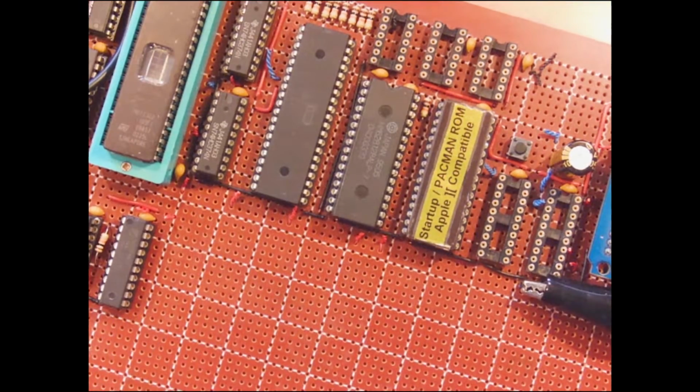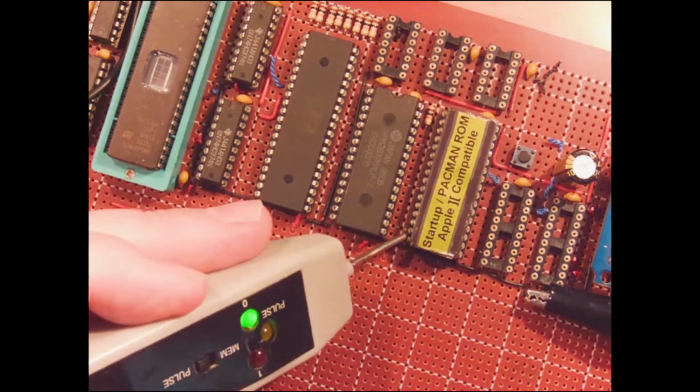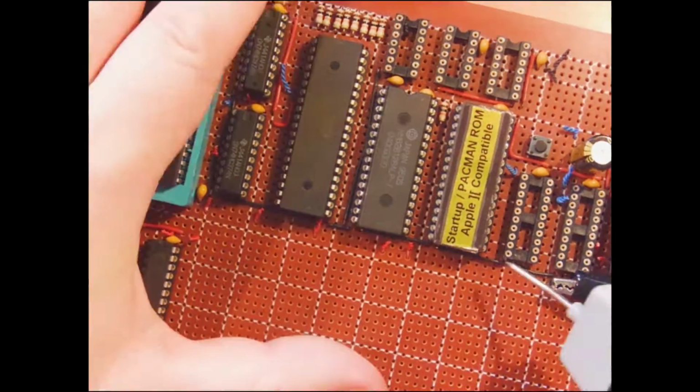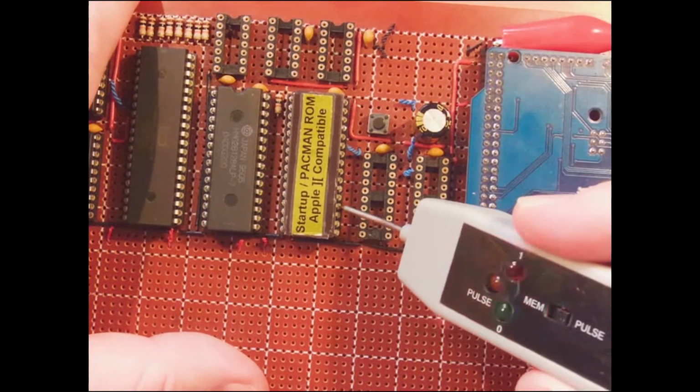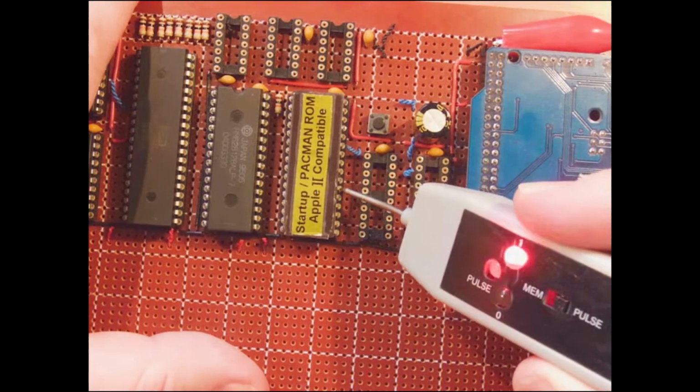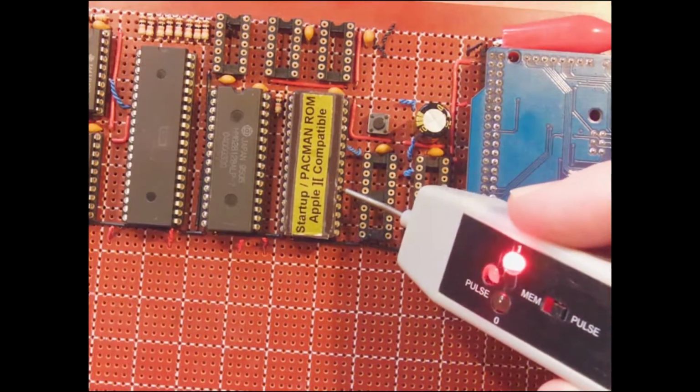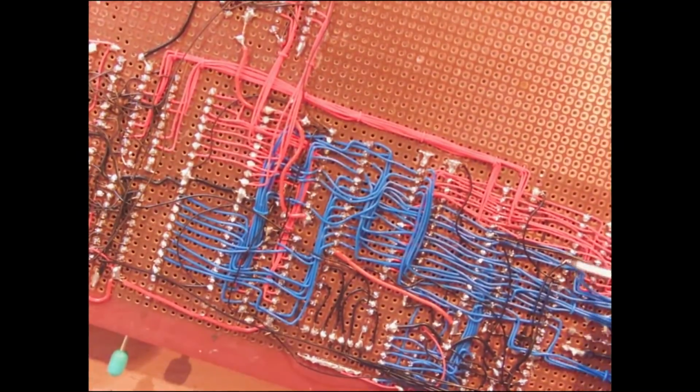D2 on the EPROM is next to ground, and I accidentally shorted it and got this pattern. Every 7th pixel's missing, so this tells me the shift register's working. The remaining data pins appear to be flipping, so that's good. The chip enable on the EPROM's high. Now that's at least part of the problem.